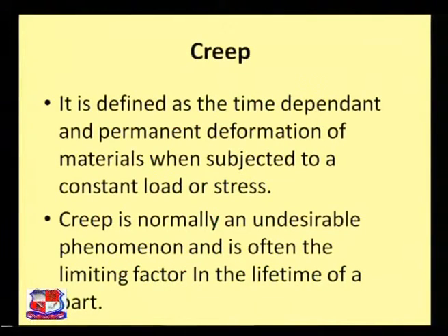Now dear students, we will try to understand the phenomenon of creep. It is defined as the time dependent and permanent deformation of materials when subjected to a constant load or stress. Creep is normally an undesirable phenomenon and is often the limiting factor in the lifetime of a part, right. Of the properties we saw earlier, a few are desirable properties, but creep is an undesirable property which limits the lifespan of any particular part, right.